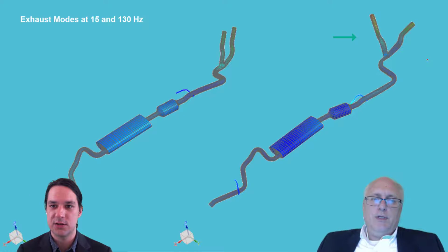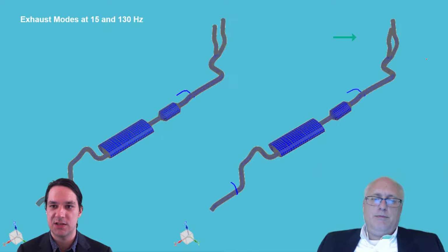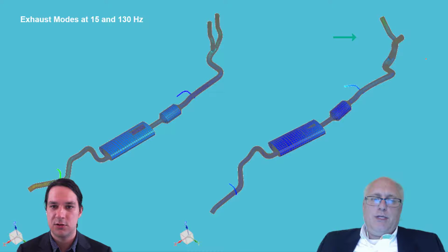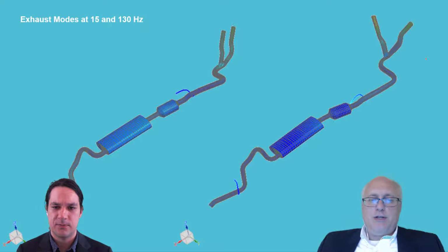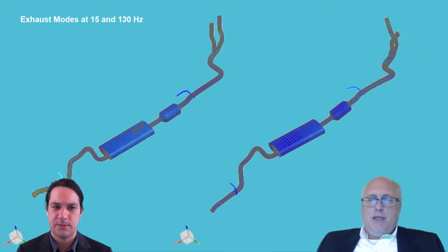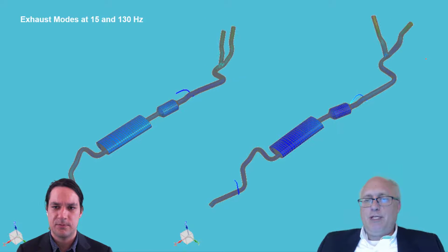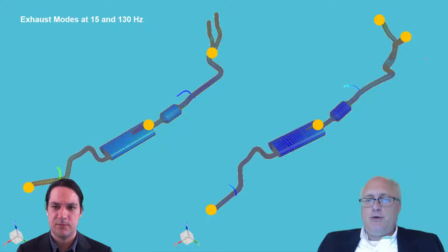You'd probably want a point on each of the pieces of that pipe. Yeah, the mode shape on the left is the same one we had before. We decided we needed 3 minimum. But now we have a more complex mode shape, higher frequency on the right. We're going to need a few more points. So something like this, at least 4 or 5 points, I would wager, are needed in total to uniquely distinguish these modes.